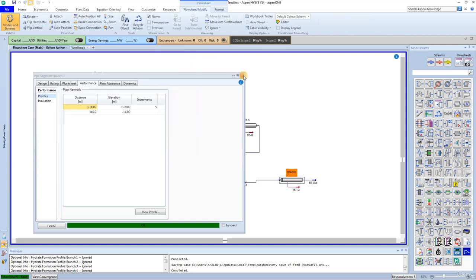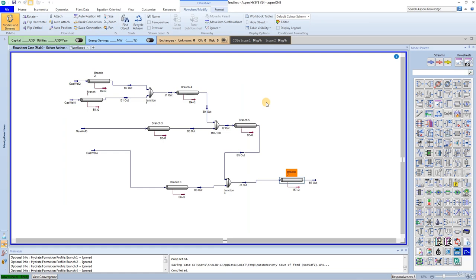Task 3. Perform flow assurance studies. The HYSYS pipe segment features 5 powerful flow assurance calculation capabilities. These calculations check the physical structures of the pipe itself versus the predicted wear caused by the type of fluid being conveyed. This allows the process simulator to quickly and easily judge the viability of a pipeline over time based on whatever fluid is being modeled.